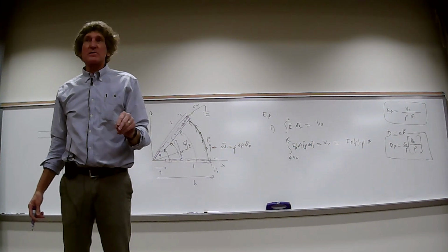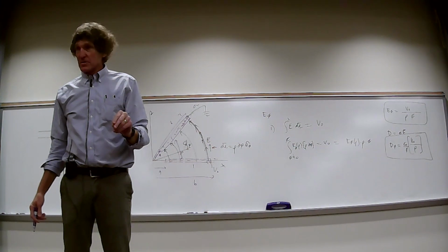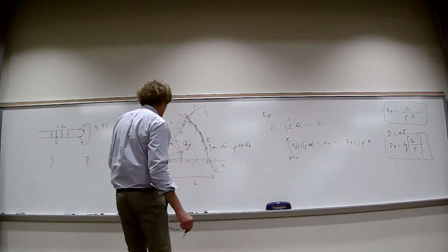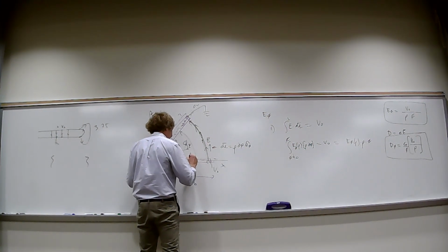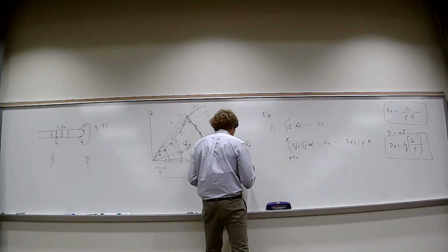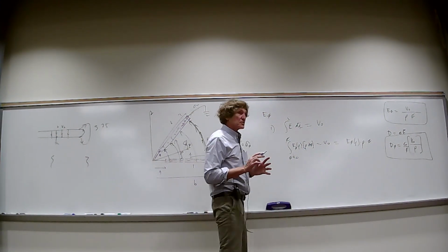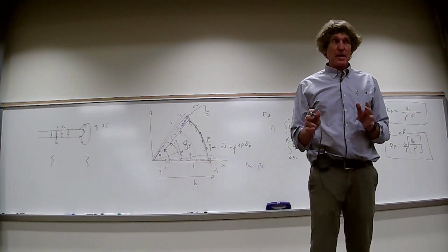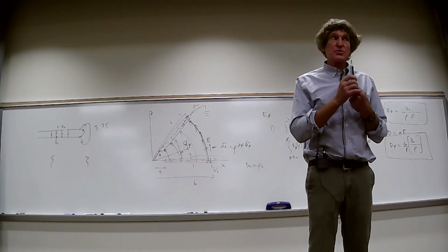What are the units of charge density? Coulombs per meter squared, aren't they? As a matter of fact, and we'll talk about this, the D field on this surface right here, D normal is equal to rho s, and that's true on a perfect conducting surface. It's not true for a dielectric, but D normal is the charge density.